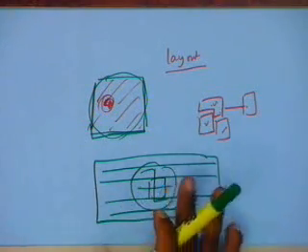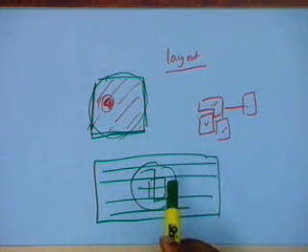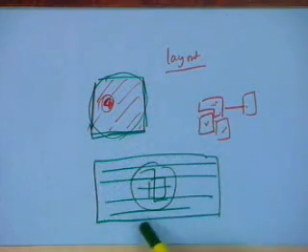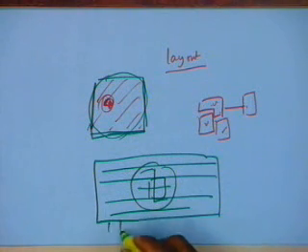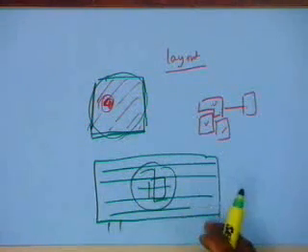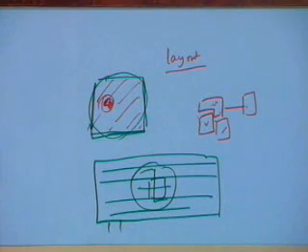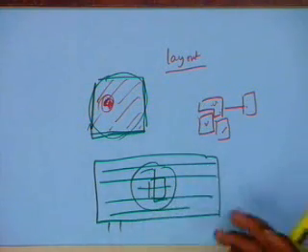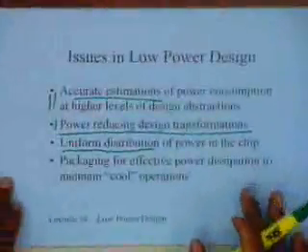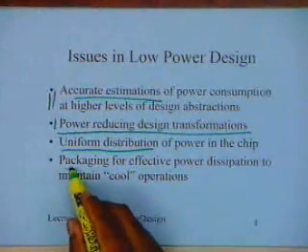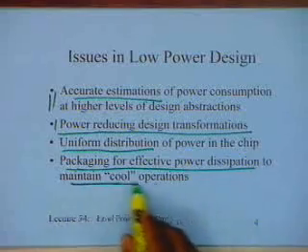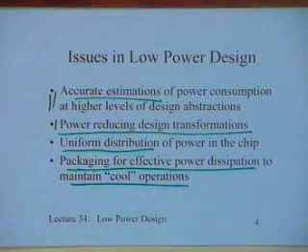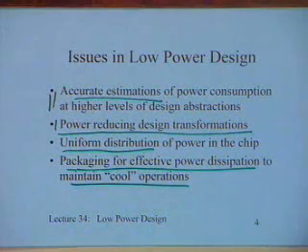Of course there are a lot of pins, so I need to take the wires and the interconnections, but today even more than the interconnections, the area is governed by the power that needs to be dissipated, because one needs to take the power off from the chip and put it onto the environment. So there is a lot of mechanical engineering and also material science that goes into designing good packaging, good conducting materials and so on.